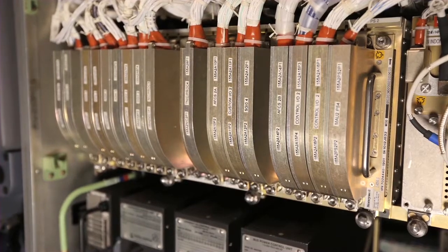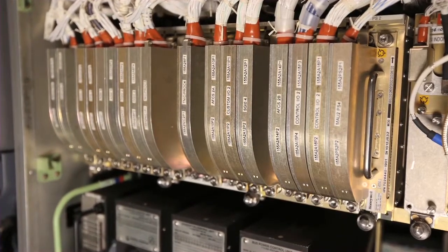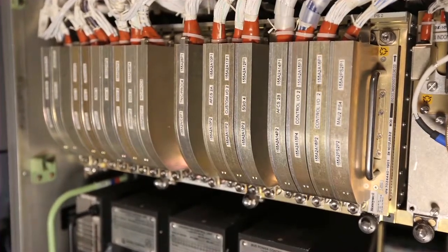When there are only 1 or 2 modules that need to be loaded, for example, if you've replaced a module on the MAU, a target load can be performed in place of a full load. You can perform a target load on any module that is on the LAN and can accept the data load. It's normally used in a maintenance situation when a module has been replaced or swapped as part of a maintenance activity.